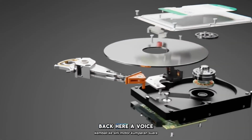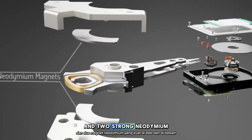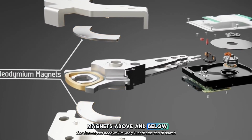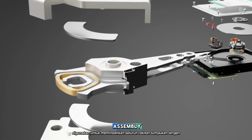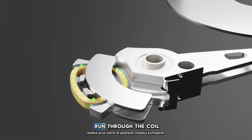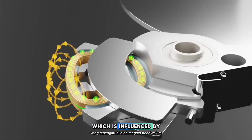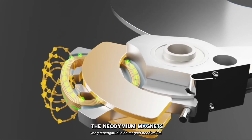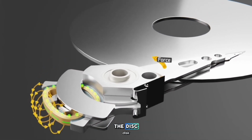Back here, a voice coil motor composed of a coil of wire and two strong neodymium magnets above and below. It's used to move the entire arm stack assembly. When electric current is run through the coil, it creates an electromagnet, which is influenced by the neodymium magnets, thus generating a force that causes the arm to move across the disc.